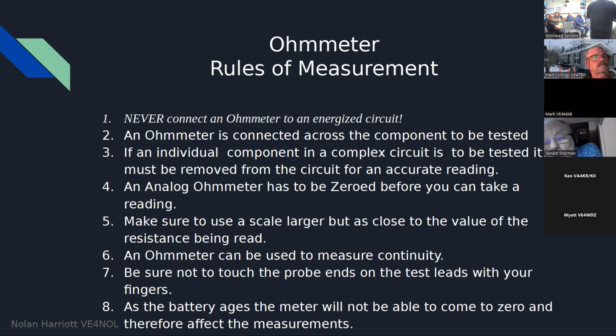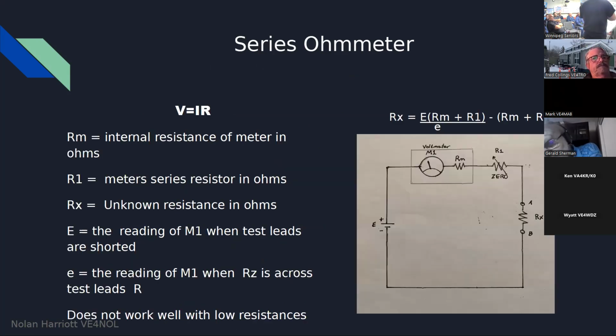And get to a point where your battery gets so low that you won't be able to zero the meter. So make sure that your meter does zero before making measurements, or you won't be able to trust the measurements that you're making.